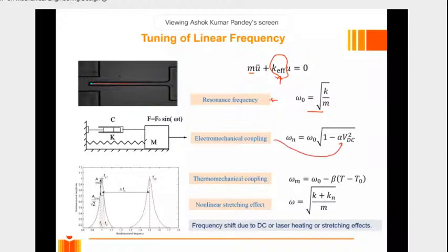So if you increase VDC in that actuation, you see that the frequency reduces, right? Because it is a minus, the frequency may shift from this portion to this portion. Okay, so because of the VDC effect, that we call the electrostatic softening effect. Okay, this is called the softening effect. And so this is one way of doing tuning.